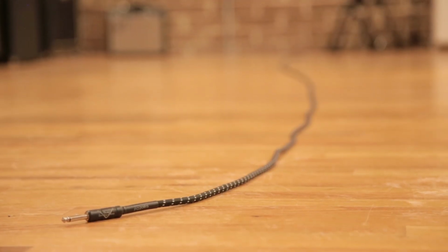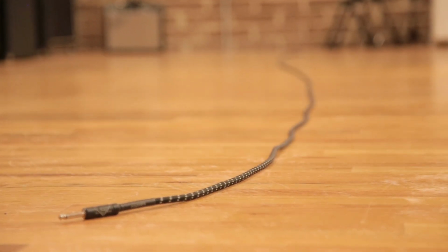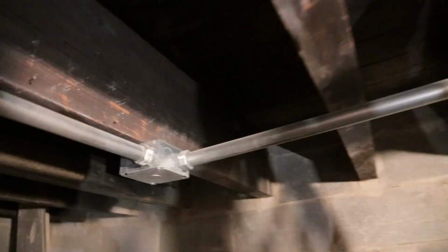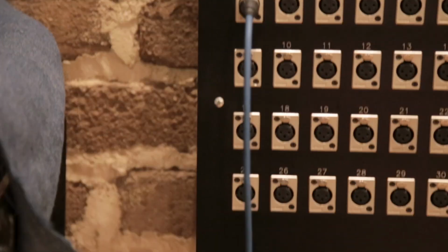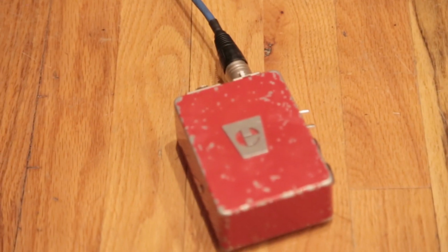A guitar output or other unbalanced signal is subject to signal degradation in runs longer than about 20 feet. Not long enough to make it two or three rooms away where your amp is. A balanced, low impedance signal, on the other hand, can be run up to hundreds of yards before you'd encounter that risk. The low impedance and balancing of a signal, like a mic level signal, is what preserves the signal quality over a long run.